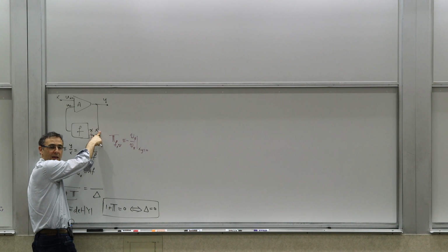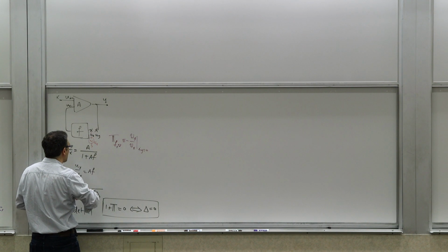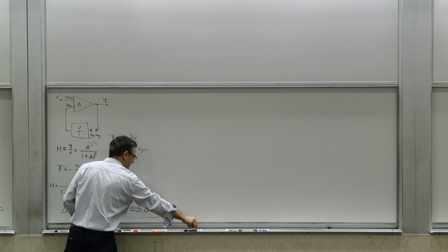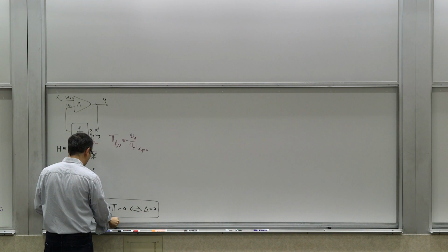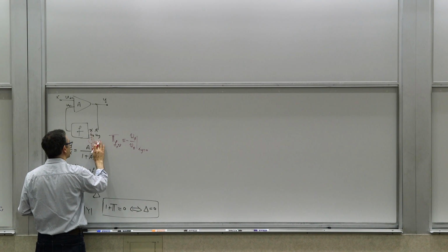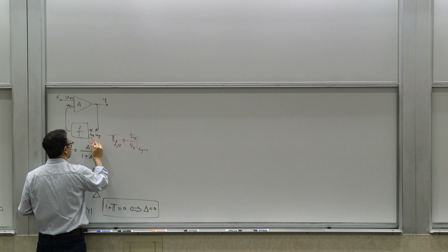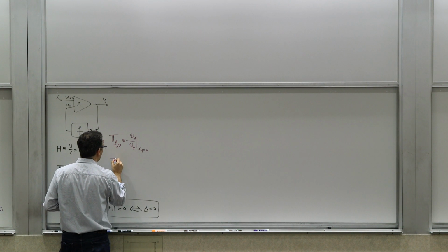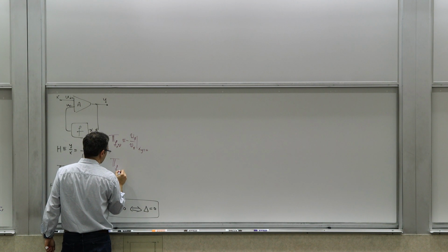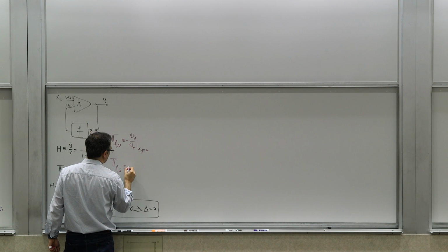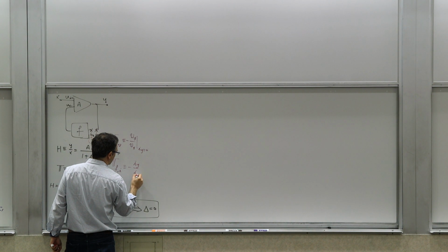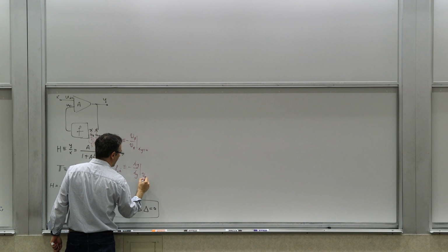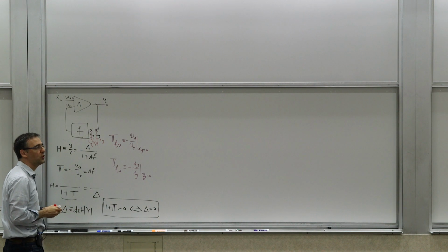And then we said, okay, now also apply a current source Ix, and short circuit this and see what is the current coming back, Iy. And that ratio, we said, was the forward current loop gain, when Vy was 0. So we had these two things defined.